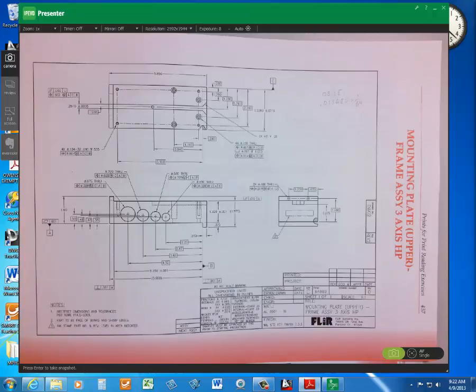Starting at the smallest for the hole, 0.187, your position tolerance would be what? It's right next to the circle M. Your positional tolerance for the smallest hole of 0.187 will be, since it's circle M,